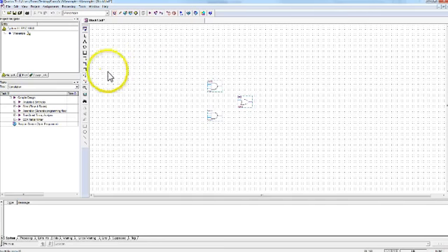The best way for me to connect the gates is to use the orthogonal node tool. And that's drawing a wire. The way the orthogonal node tool works is that you can drag out and then make 1 right angle turn. And then if you need to make another right angle turn, you'll have to unclick and then click again and slide over like that. So again, I'm going to click here, and then I'm going to drag up, take 1 right turn, unclick, click again to complete that.